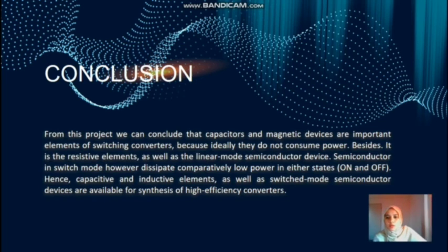From this project, we can conclude that capacitors and magnetic devices are important elements of switching converters because ideally they do not consume power, besides the resistive elements as well as the linear mode semiconductor devices. Semiconductors in switch mode, however, dissipate comparatively low power in either state, on and off.